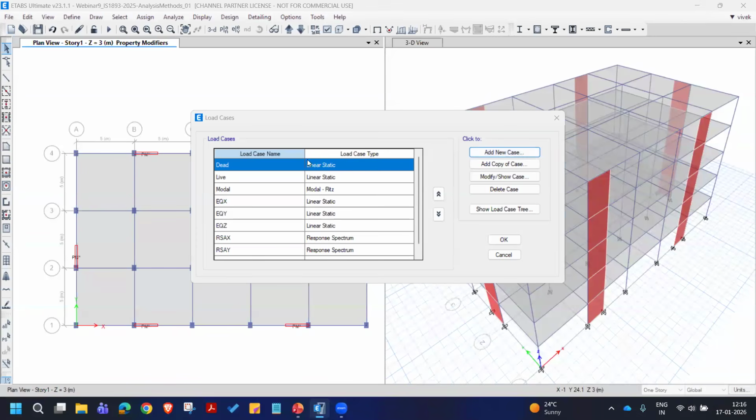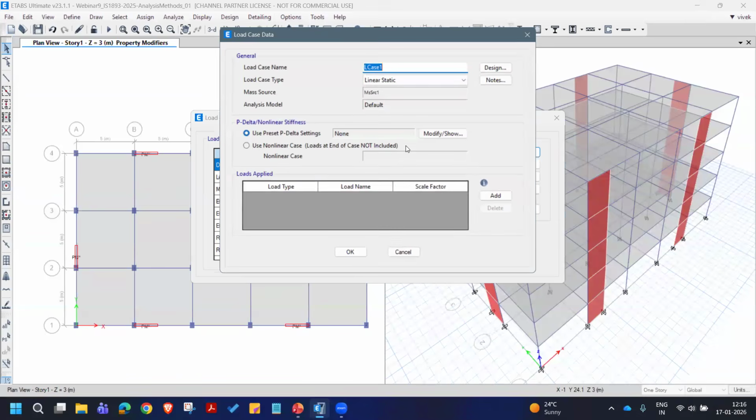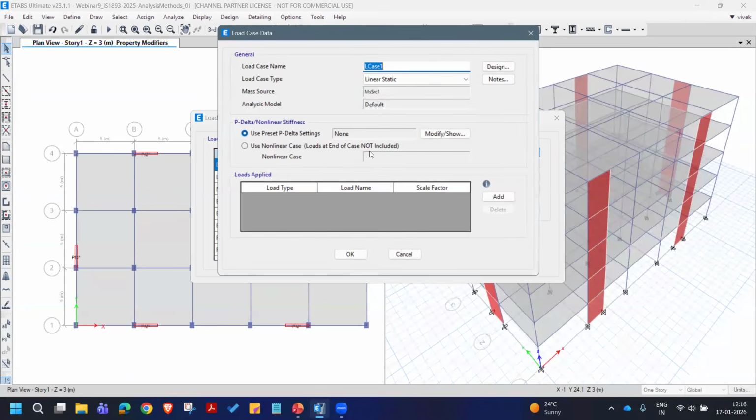So load pattern is acceleration. In U1, function is function 1, the response spectrum matched time history. The scale factor will be 9810, the G value, and it will be based on this modal case. The transient type motion and then number of output time steps.